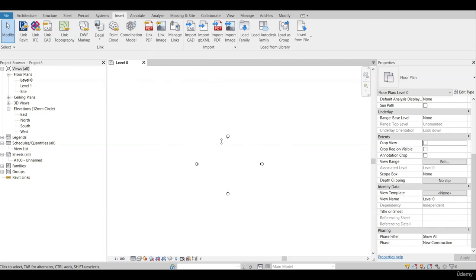But the same, if you just select and opt for the import option, then you have to recheck and link or re-import the files into Revit. So there is a difference between linking and importing. So let's check either of them. We have exported CAD format as well as the IFC, and also we have a Revit file as well.